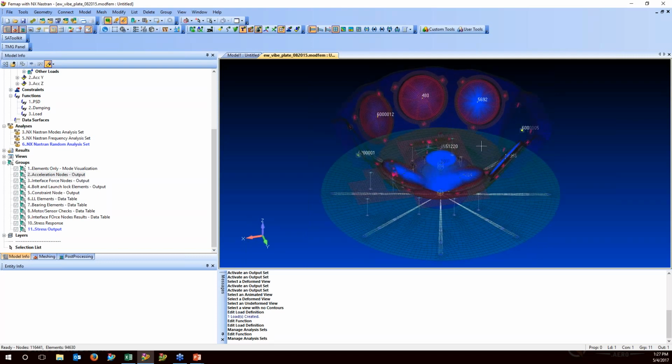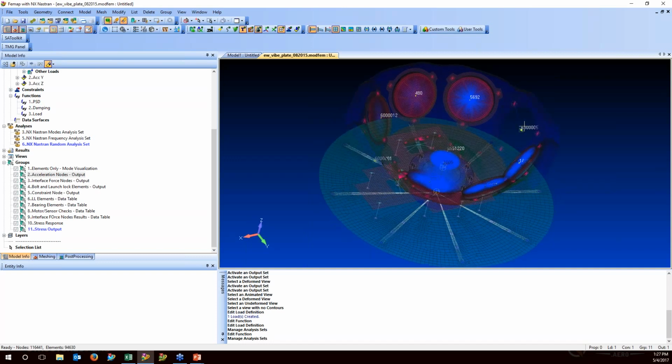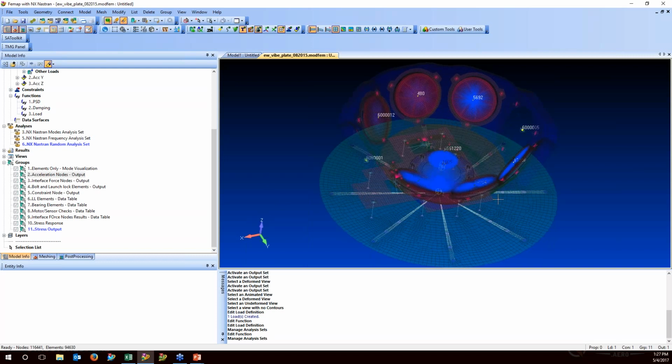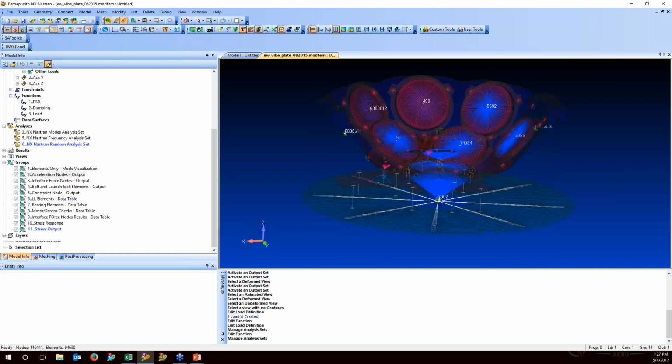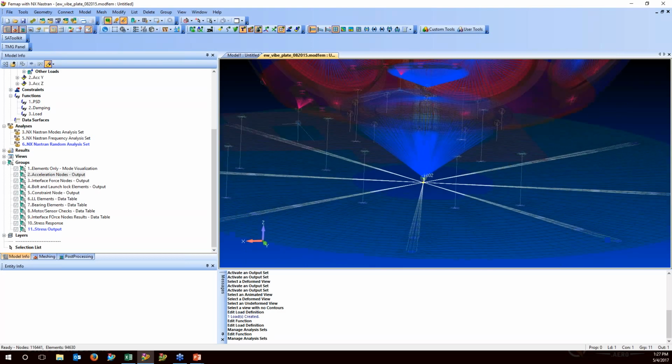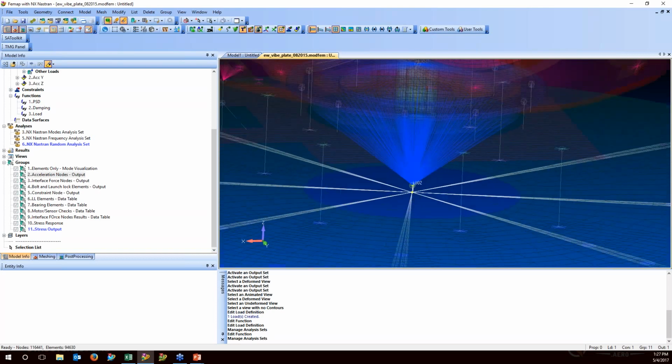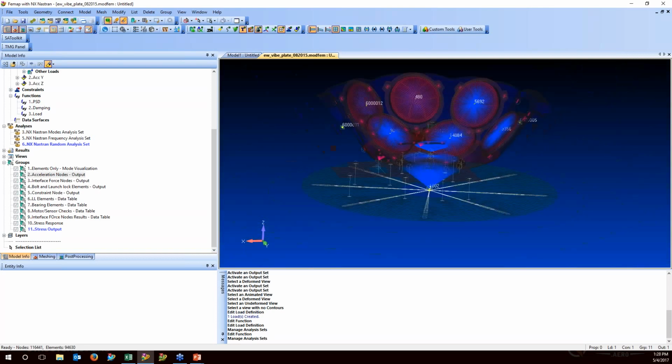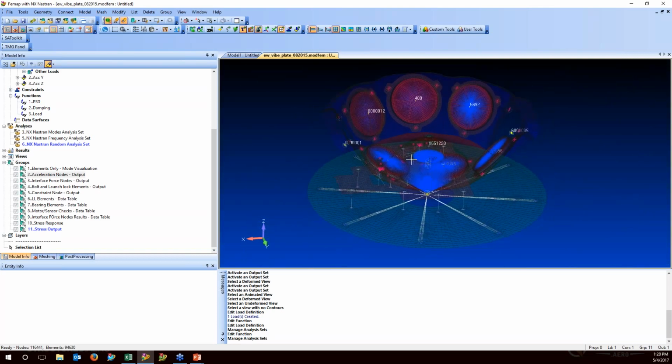We might be interested in understanding what accelerations are imposed on the system due to different loads during our load environment. One very important thing is you always want to include the input location. In this case, you've included node 1 here, where our constraint location is. And we'll discuss that here very shortly.